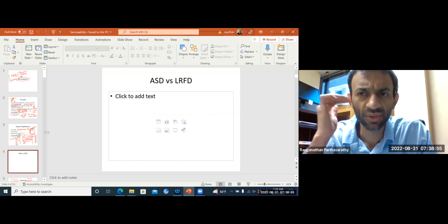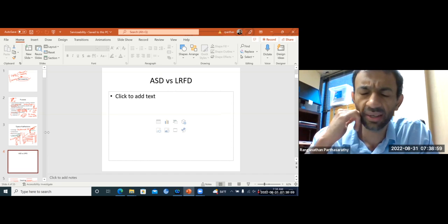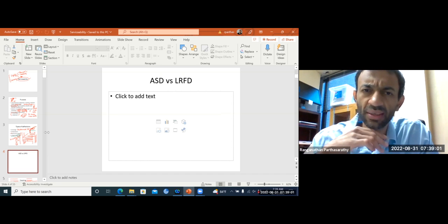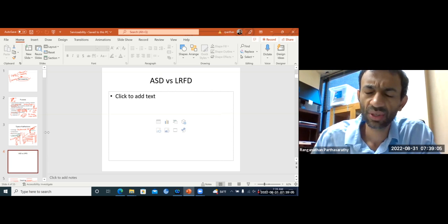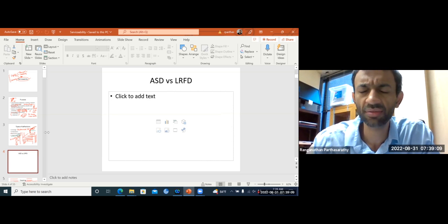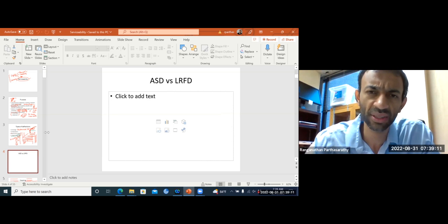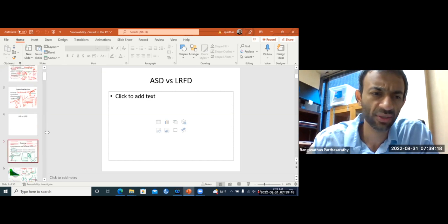This you all know, you can even listen to the recording. In allowable stress design, you keep everything in the linear elastic range, so you don't need to worry too much about serviceability. However, in LRFD, we are using the actual ultimate strengths of the material, so we do need to especially consider serviceability.